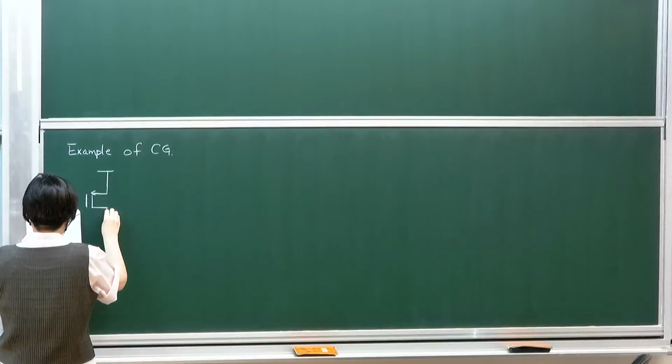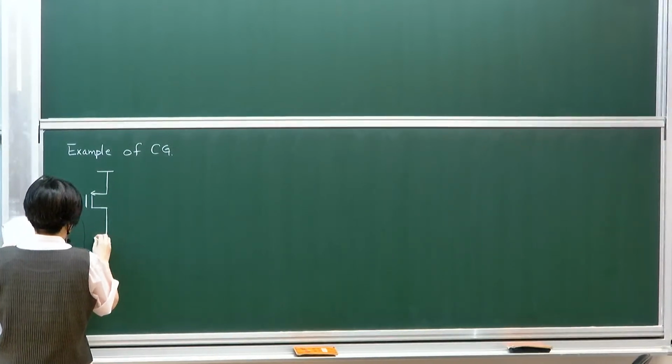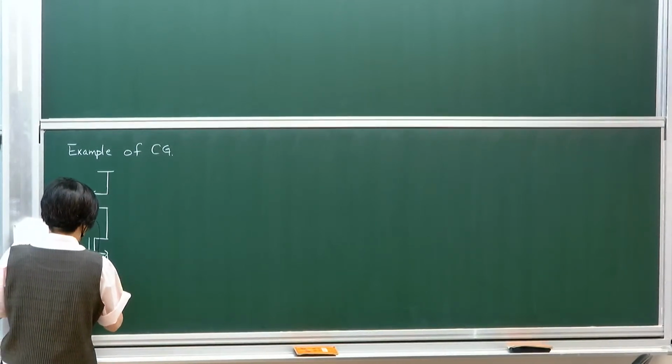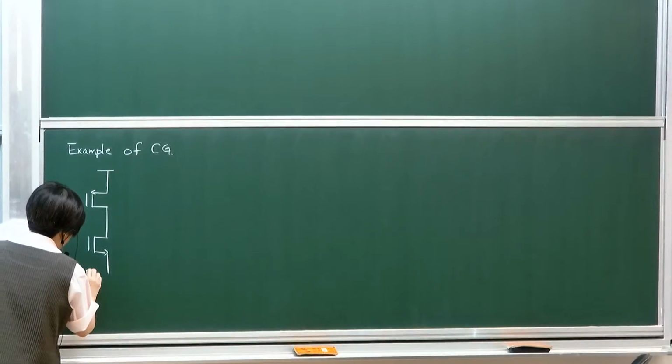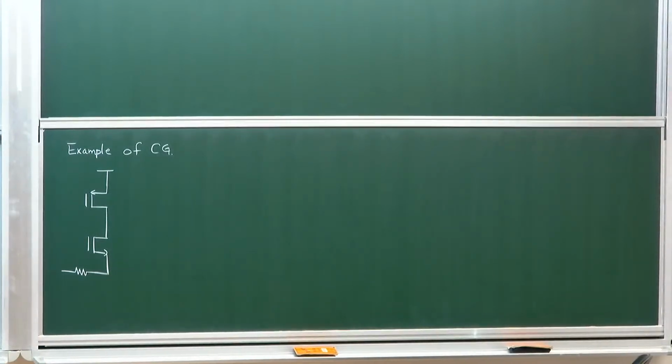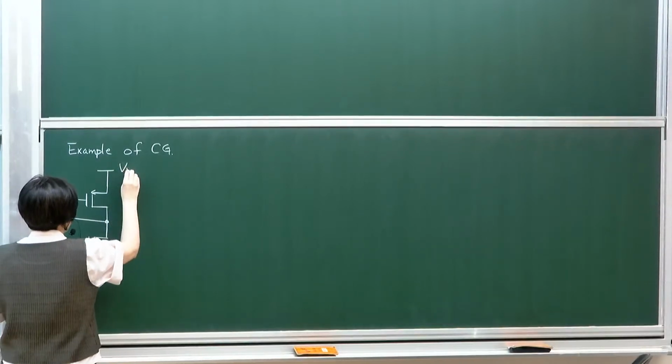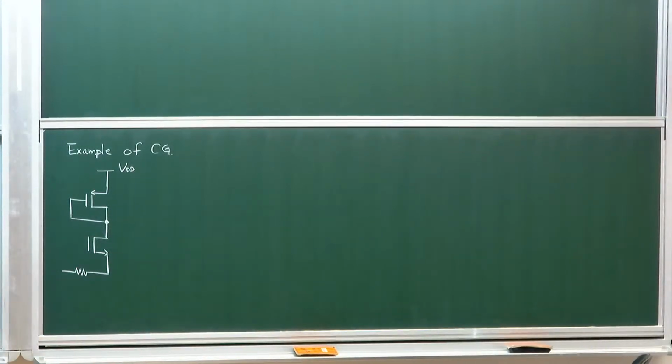So in this case, I'm also using the worst case scenario. The reason why it's called the worst case scenario is that it actually has the highest parasitic capacitance. So I'm going to use the diode-connected example again. This would then give you the highest parasitic capacitance in the circuit. So let's just use the same architecture, but instead of having an RD, you're using a diode-connected load.